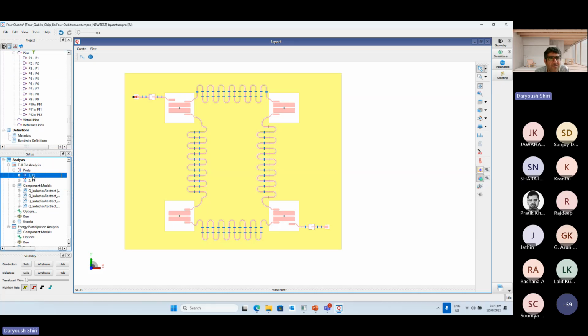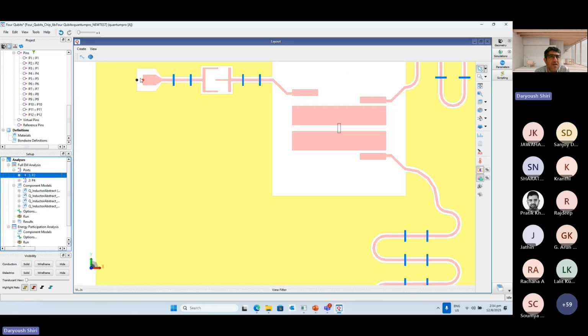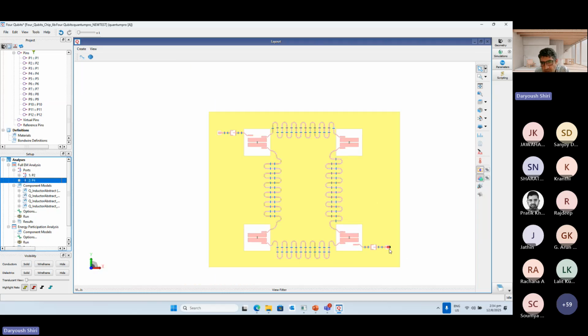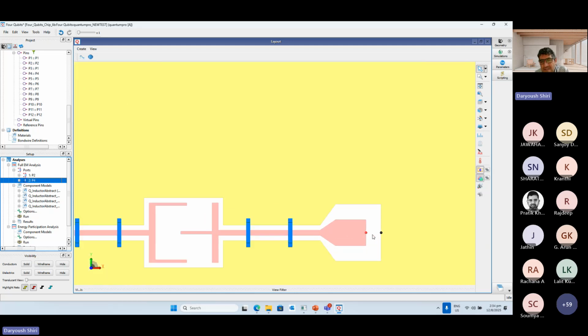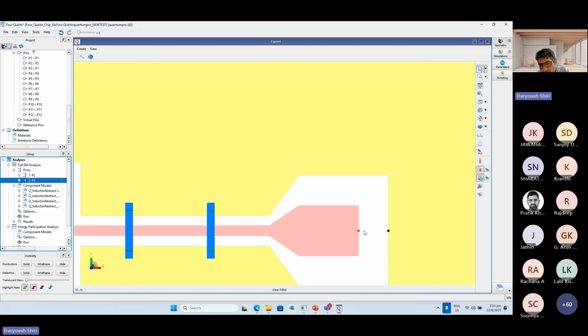And if you click on that afterwards, you will see what I meant by the positive part or negative part. And then the other one is here. So this is where you inject the signal. For example, in ANSYS HFSS, you have to draw a line here or put a sheet here, and tell the simulator that you need a lumped port here and inject the signal from here. And then options.